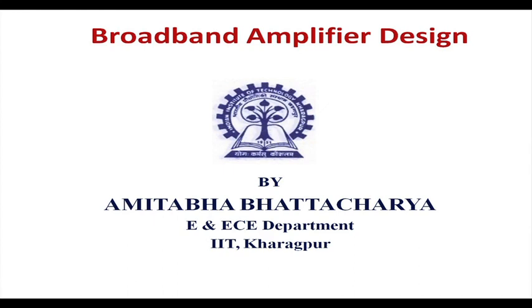Welcome to today's lecture. Today we are continuing our amplifier design lectures. So, today we will see another class of amplifier which are broadband. We have seen that if we do conjugate matching, that match and also S parameters of any transistor are true for any particular frequency, but many times we know that our baseband signal is a band of signal, it is not a spot frequency.